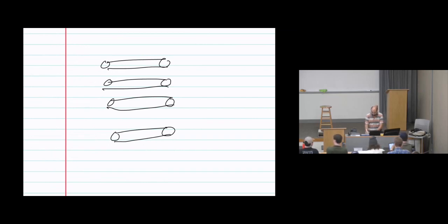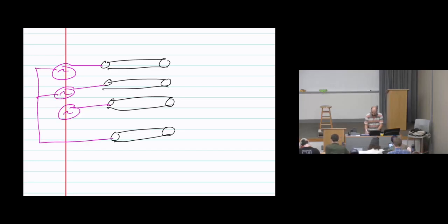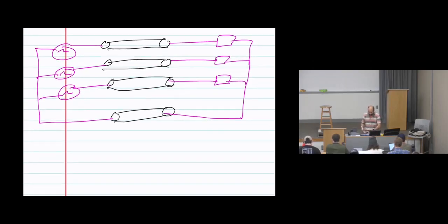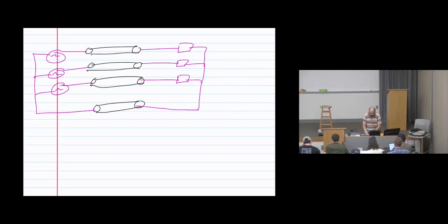Basically, there will be 3 sources. So here is a voltage source, here is a voltage source, here is a voltage source, and the returning current goes through the neutral. And to the load, we have the same thing, Y, where here is an impedance, an impedance for each phase. This is called Y or star connection. Why is it called Y or star? Basically, I can remodel or rewrite this as a Y shape.